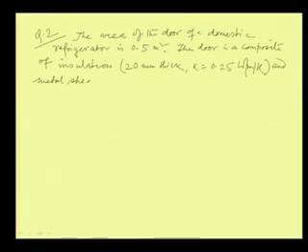We know that there is a metal sheet on the outer side of the refrigerator, and the inner side is the insulation part, which is 20 millimeter thick, that means 2 centimeter thick, and the metal sheet, which is say 2 millimeter thick, and K is 40 watt per meter per Kelvin.